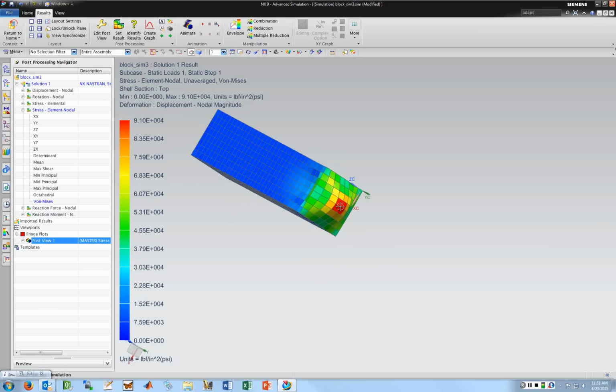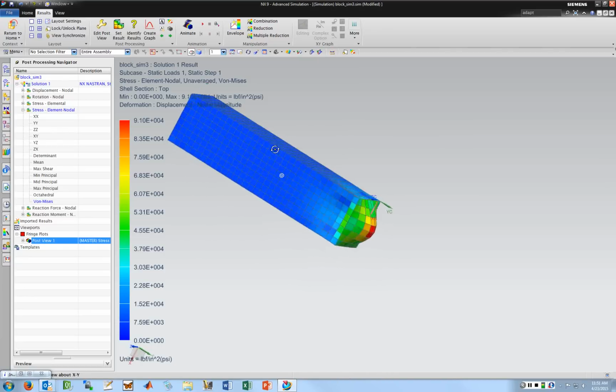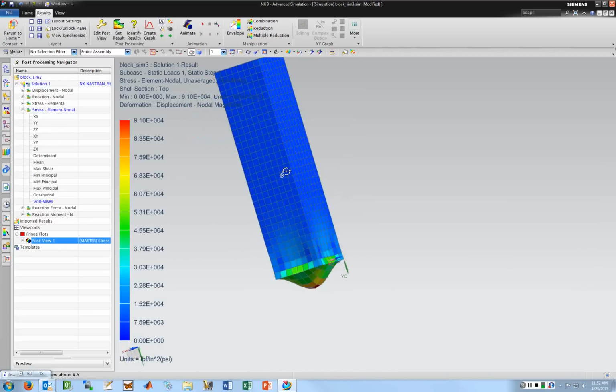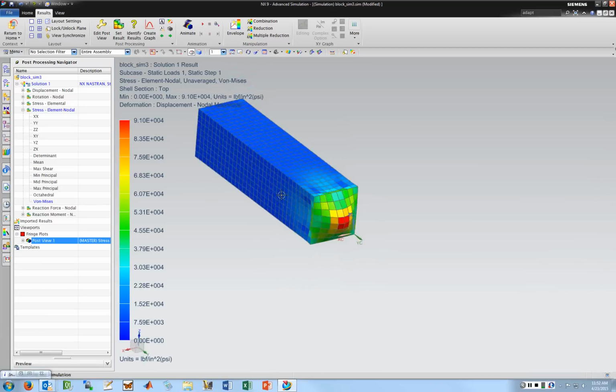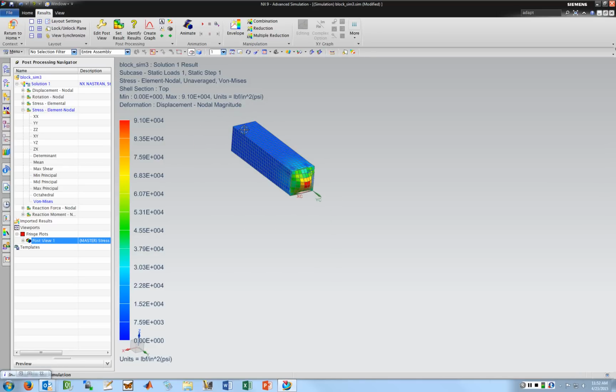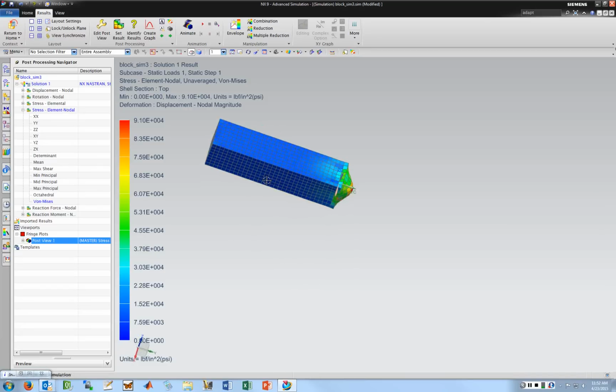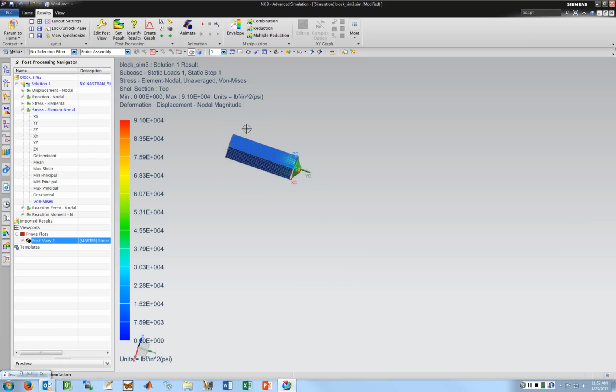But it's kind of a strange loading situation. I guess I could treat it as a pressure vessel, but I probably would use a different kind of load. I'd probably use a pressure instead of a force. But they end up being the same thing if you calculate the surface area for it. But so that's just a really simple shell mesh. This is really helpful for doing tube frame structures like space frames. Most things are just simple cross sections, and it's really easy to do.